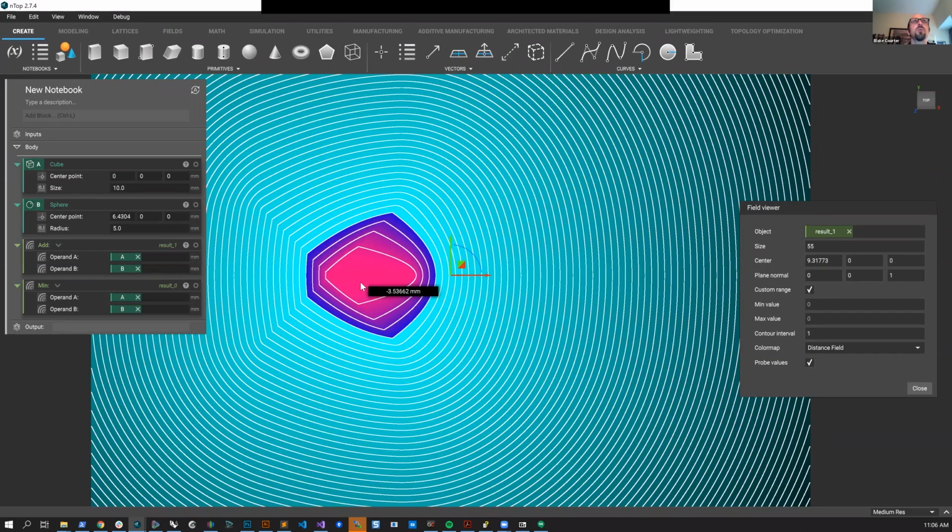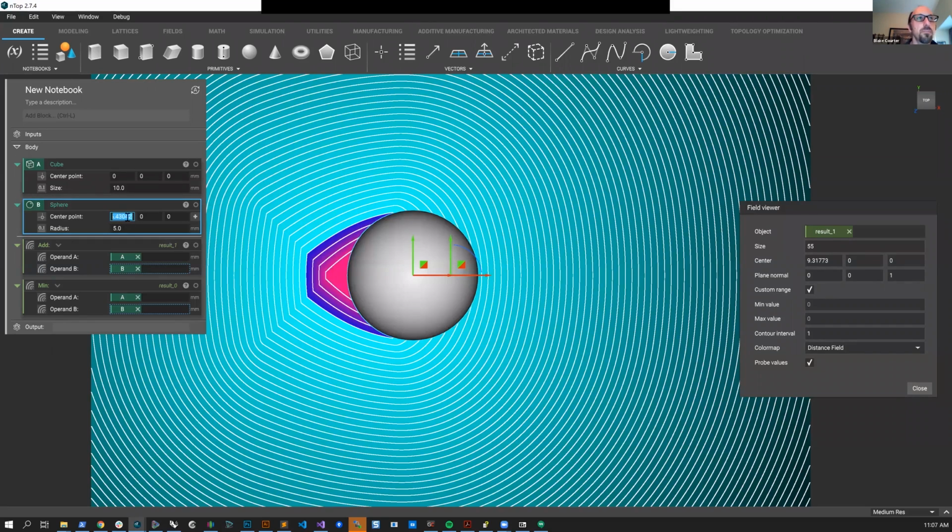It is. For example, if you were trying to make a scale model of an assembly and you wanted to have all the parts have nice little slide fits to put on a desktop, you can easily remove all the interferences from your model and make something that prints at a different scale. Or if you want to force a press fit, all these things, you have complete control over clearance and interference when you're dealing with implicits. That's just a little aside. Okay.